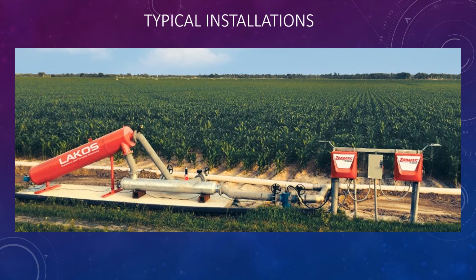But it was used as a primary filter to protect this pivot corner, which is installed with subsurface drip, from plugging up the system. But I can guarantee you, if there's any silts, they're getting right through that, and they're impacting this system. And I can tell you, they don't put flush manifolds, so they have to go out to every one of these lines at the edge of the circle and flush it manually. And it's quite a pain in the butt.